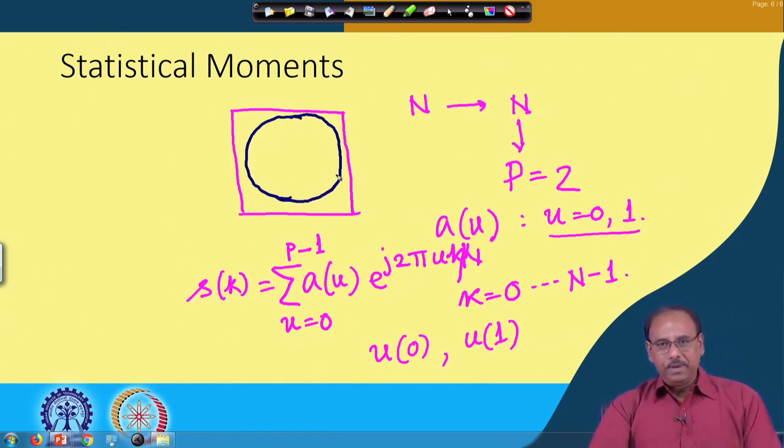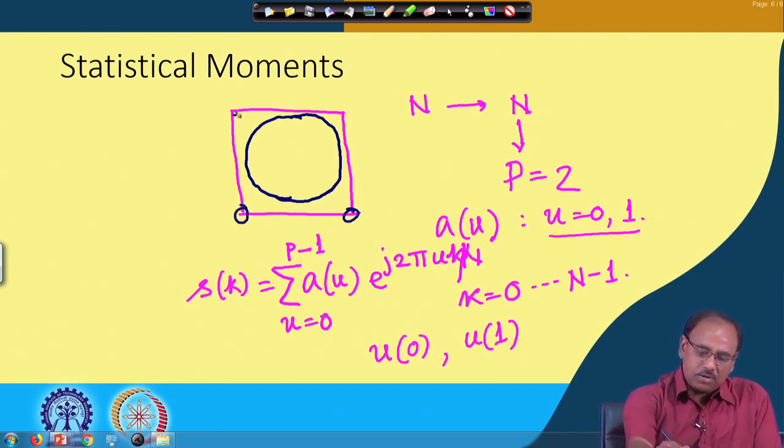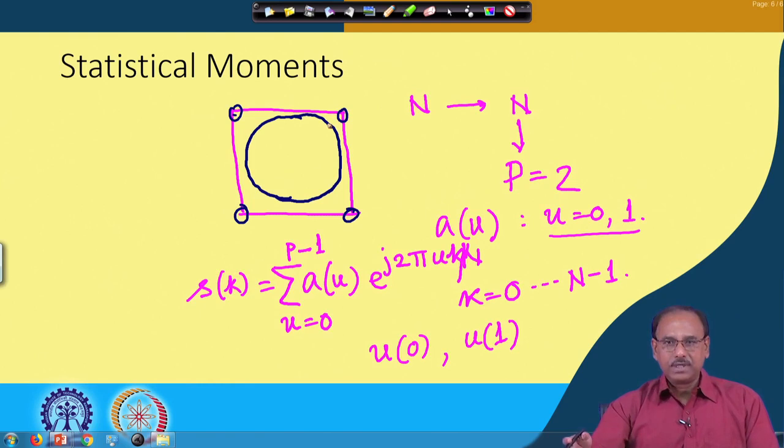Which will be a circular shape, because as I said, low order coefficients give you only the trend of the signal, but the high order coefficients give you the details of the signal. In a square shape, the details mean the presence of all these corners or vertices. So, as I have truncated all the high order coefficients, this detailed information in the reconstructed signal is lost.